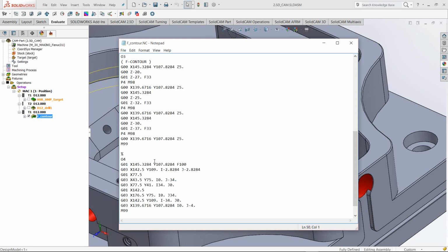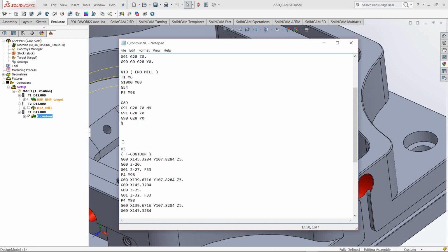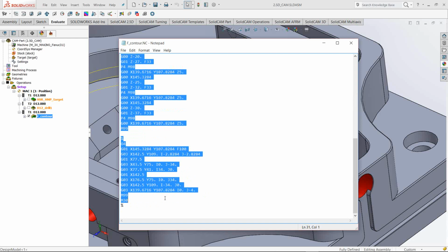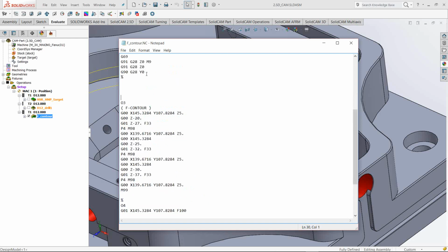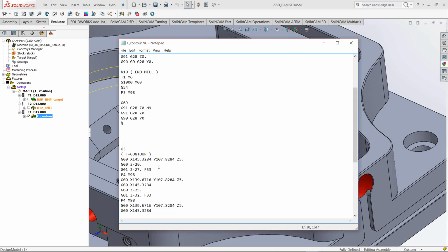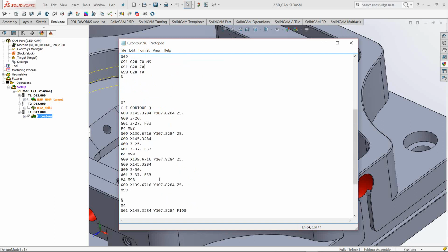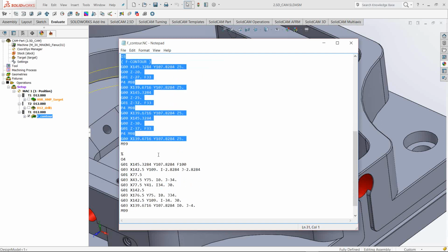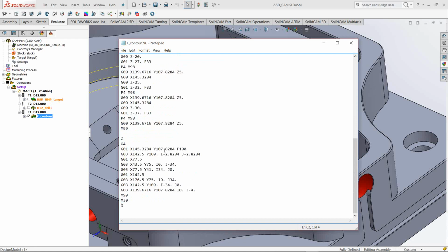And now the third option that we are supporting in SolidCAM is to not output all of those subroutines after the main program, but actually to print them inside the main program and just call these subroutines, like generated on the job level.